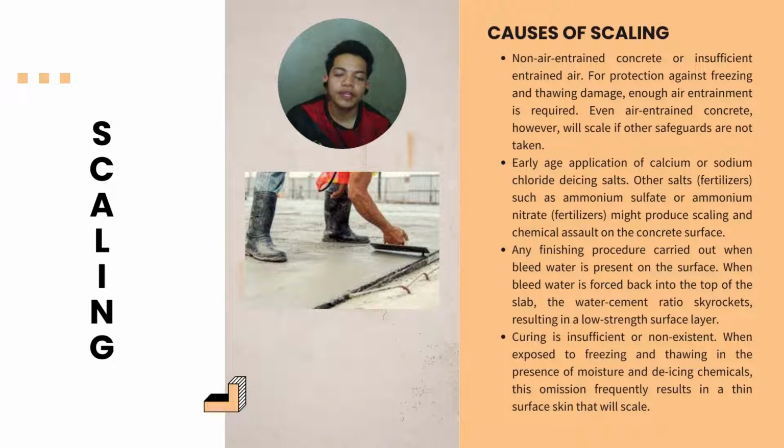Do you know what the causes of scaling are? Scaling happens because of non-air-entrained concrete or insufficient entrained air. For protection against freezing and thawing damage, enough entrained air is required. Even air-entrained concrete, however, will scale if other safeguards are not taken.